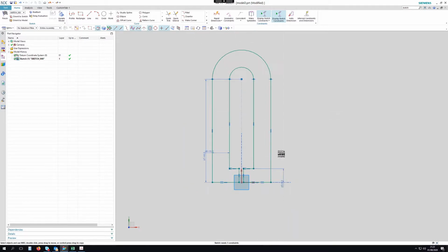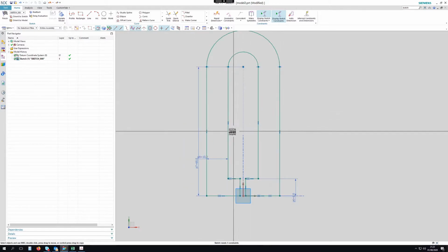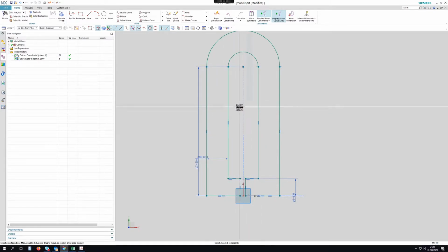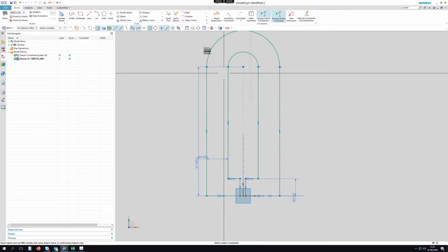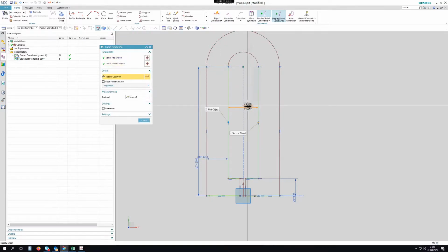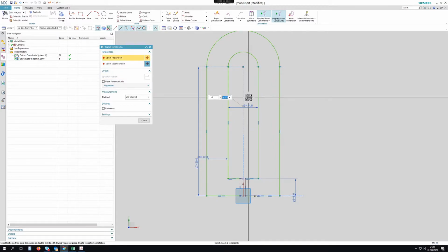There we go. And I think I made that 38. So this wants to be a little bit bigger than 38. I think the general drawing tolerance on most drawings is plus or minus 0.25, so I'm going to make it a millimetre bigger overall. So from there to there, that wants to be 39.